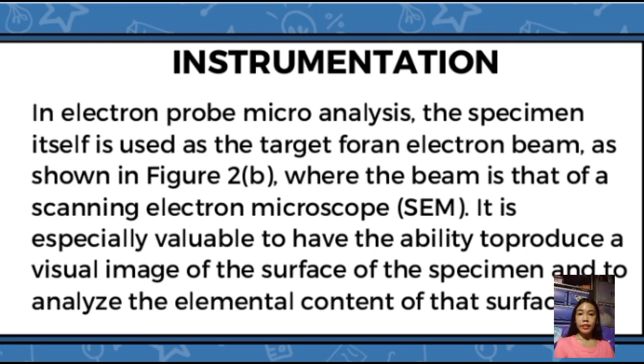A solid-state detector is employed to capture all emitted radiation at once. This capability facilitates the use of a multi-channel analyzer, which generates a series of voltage pulses that correspond to the X-ray spectrum emitted from the specimen. This method is commonly referred to as energy dispersive analysis of X-rays, or EDAX.